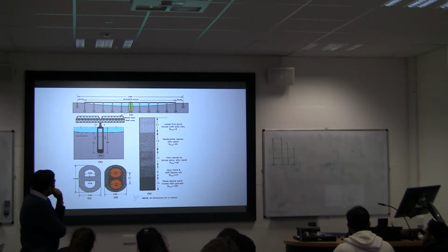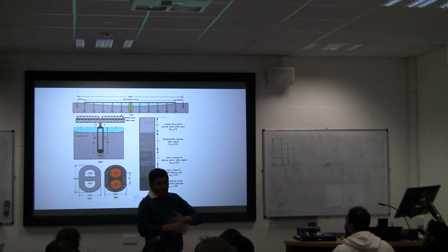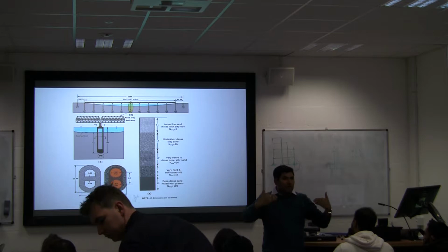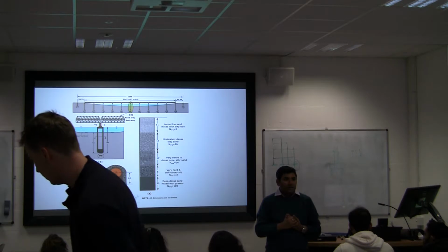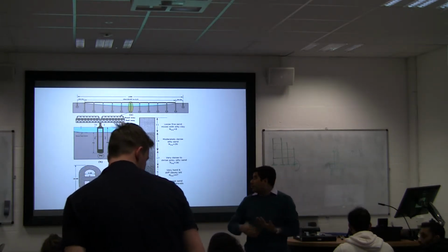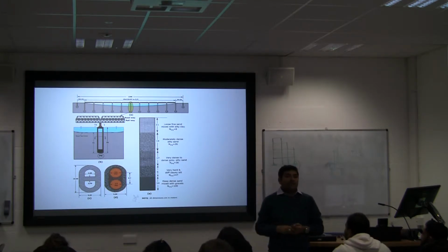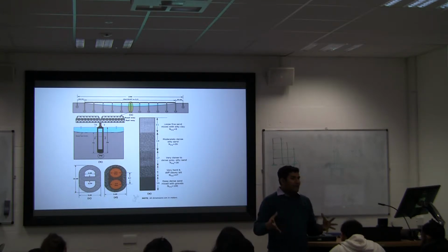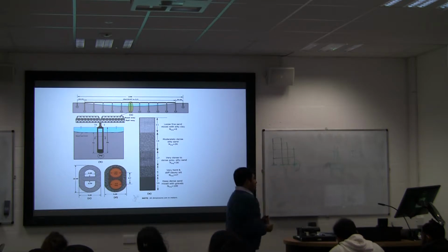So the topsoil might liquefy. In an earthquake, you will have a lower amount of embankment, so you have to make the foundation a bit deeper to take into account the extreme loads. When you do the foundation, you have to look into the different aspects, because if you're doing a bridge like this, you have to design it for a good 100 years or even more, right? And in 100 years, there can be multiple earthquakes, and you must make sure that in earthquakes it will still operate. Is there a question so far?